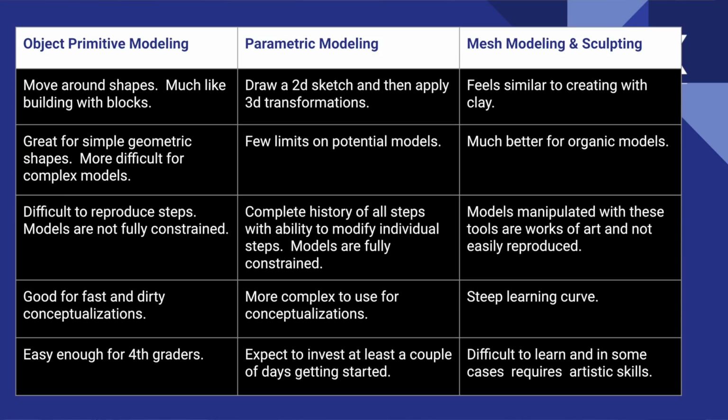You can go back to an earlier step, and I'll show you an example of this. You can change one of those parameters. In essence, the computer program will rerun all the steps and rebuild your model. So the act of creating a three-dimensional model creates a series of steps that you can reproduce at any time because you save those series of steps.